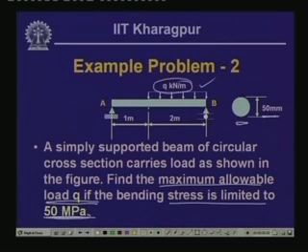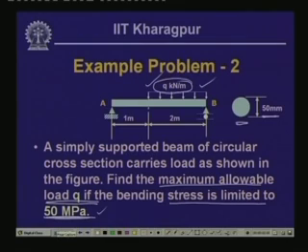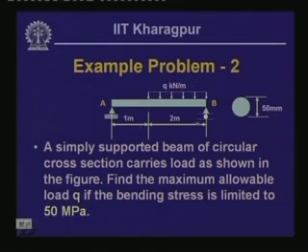So, here we will have to find the value of the load Q so that the stress does not exceed 50 megapascal. Again, as we have done earlier, we need to find the maximum bending moment. So we resort to drawing the shear force and bending moment diagrams, so that we get a clear picture of the value of the maximum bending moment and where it occurs.